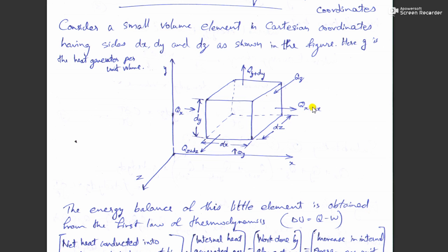So that's why this heat is called Qx plus dx. Qx is named so because when it passes through the first surface, the surface perpendicular to the heat flow, it has crossed only x distance, so it is denoted as Qx. Whereas the heat which comes out of the surface has passed through x distance and dx distance, so it is termed as Qx plus dx.